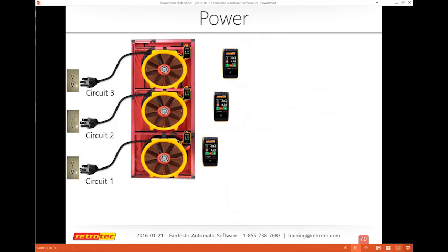The last one I'll touch base on is to make sure you have enough power for what you're going to do. Some people may decide that they need 4 fans to do a multi-fan test, but realize that there's hardly any power in the lobby or anywhere near there. Many of these fans really should have their own entire circuit, and 2 of them are going to blow a 20 amp circuit. That's common for most any fan you would use. So you need to make sure that you have the right amount of circuits, know where the breakers are, have access to them, and if you're going to have extension cords, that they're also rated for the right size.